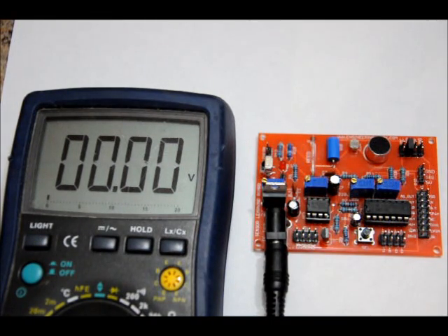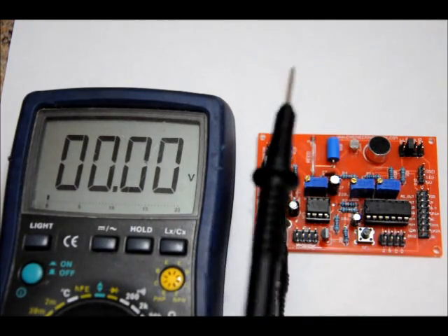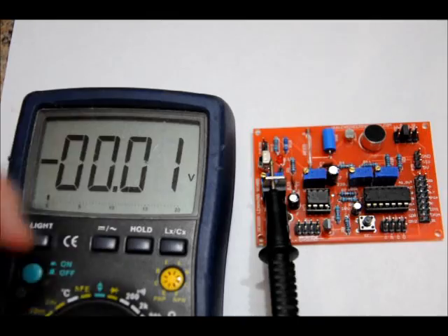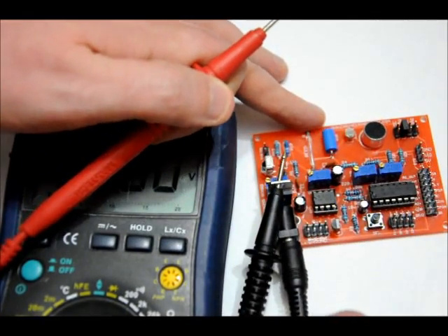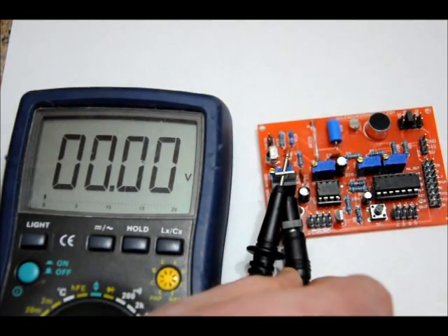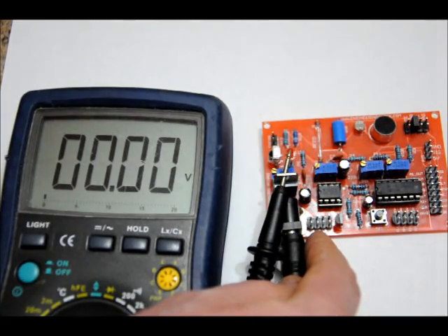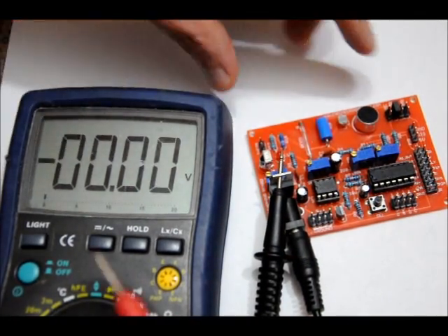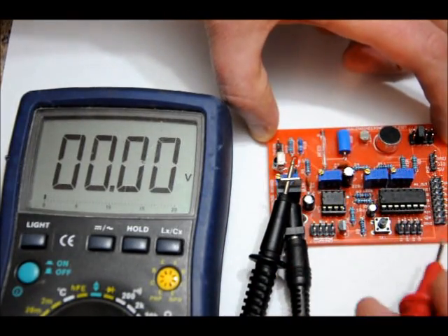So to tune, first of all, just for fun, let's take our multimeter, and you can stick the negative probe on the 7805, the back of the regulator, because that's connected to ground, or you can connect it to the ground on the power supply pin block right here. Sorry, I know it's a bit clumsy here. I'm trying to make sure that you can see what I'm doing.